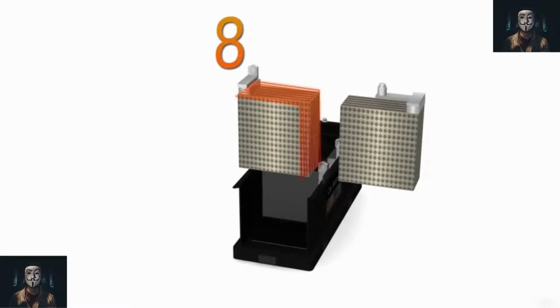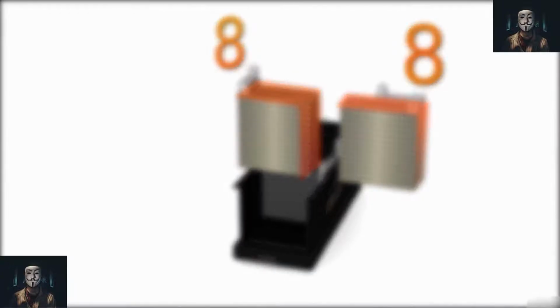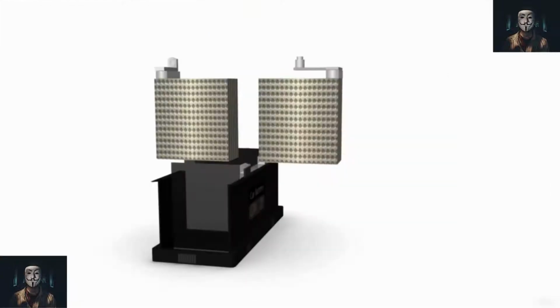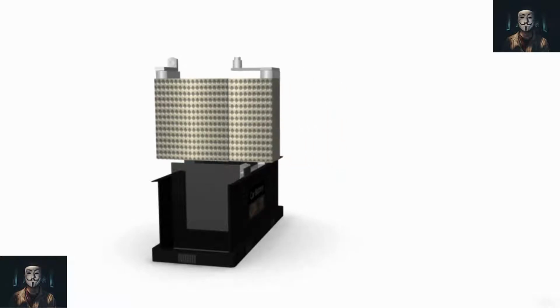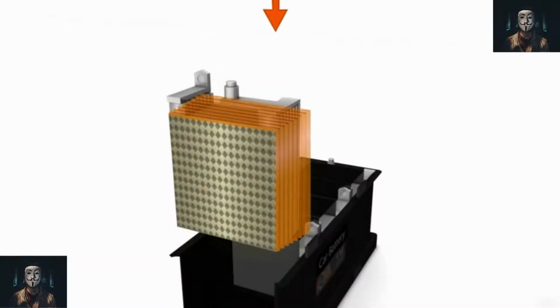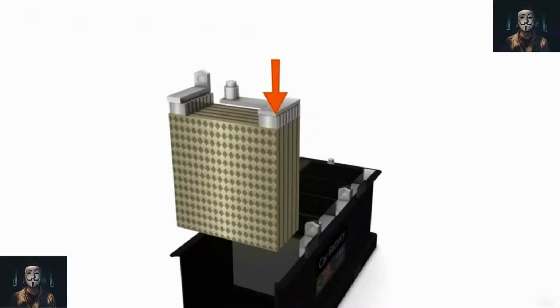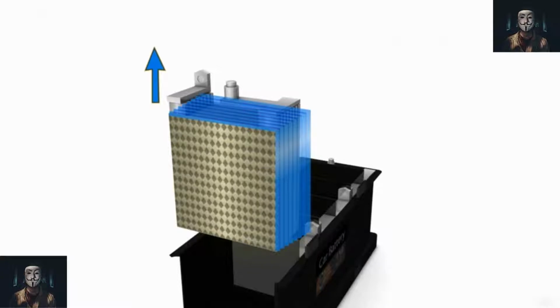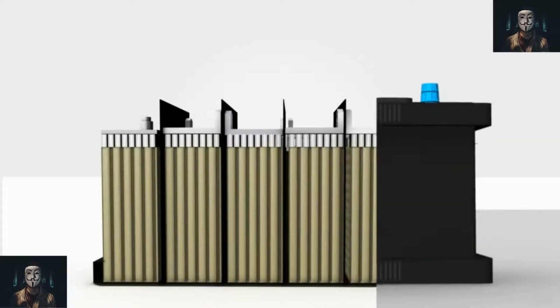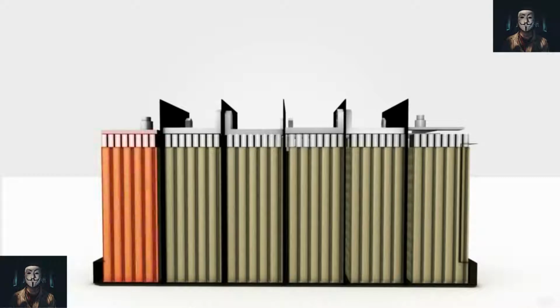A few batteries have open cells that require routine maintenance to the electrolyte level. This usually consists of adding distilled water at regular intervals. Most modern lead-acid battery designs have improved plate constructions and case design, which, with precise alternator charge control, allows maintenance-free types to be used.